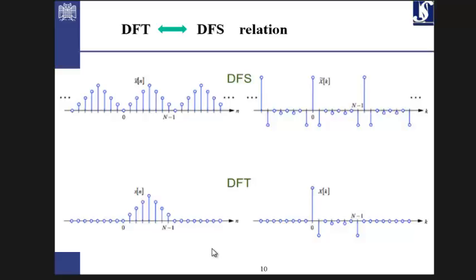Because it's periodic, it has a Fourier series. The best representation of periodic signals is the Fourier series; with just a few coefficients you can define it. So you can get these coefficients. We know that the DFS is also periodic, but you just need the first period, the major period of that. And those are the DFT coefficients of the real signal.